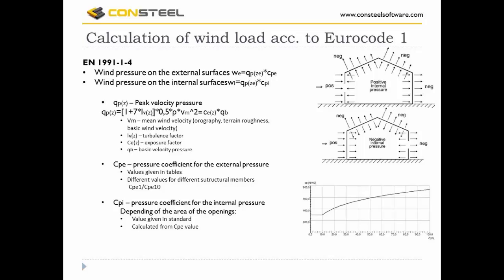For the cpe and cpi pressure coefficients: for external pressure, the values are given in tables in Eurocode, and for the internal pressure coefficient, values are also given in the standard. In other cases, it can also be calculated from the cpe external pressure coefficient factors.